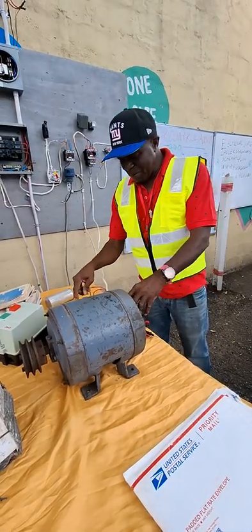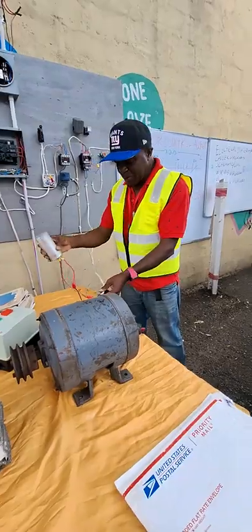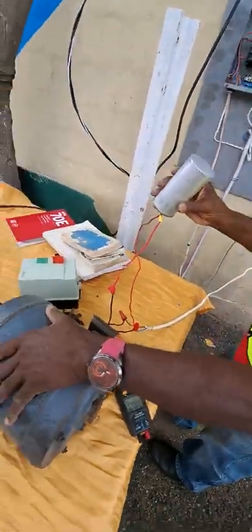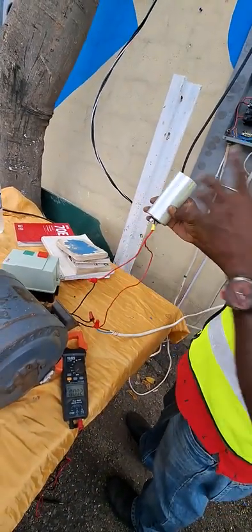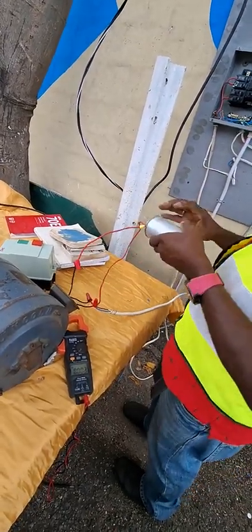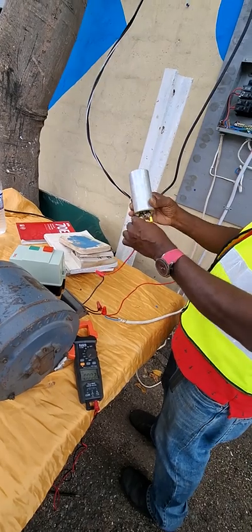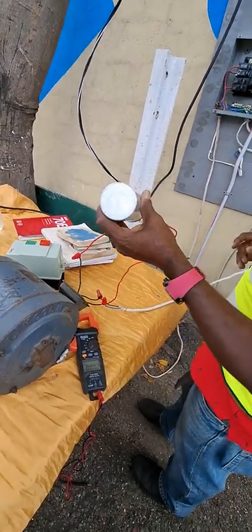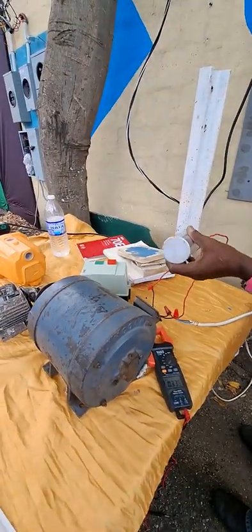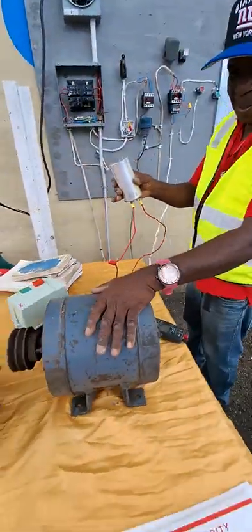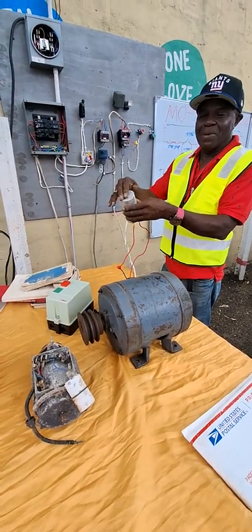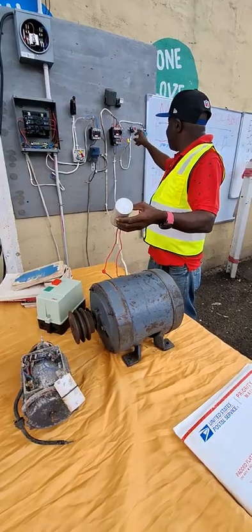And remember now, let me show them how to set up again. Youngsters, we have a 3-phase motor. However, I don't have a 3-phase supply here. I have a single phase, but I still get the motor going by incorporating this capacitor to provide a third leg and get my motor to run. So here my motor is running. This is a 3-phase motor, however, it is getting single phase with the aid of the capacitor to get it running. So I start my motor.